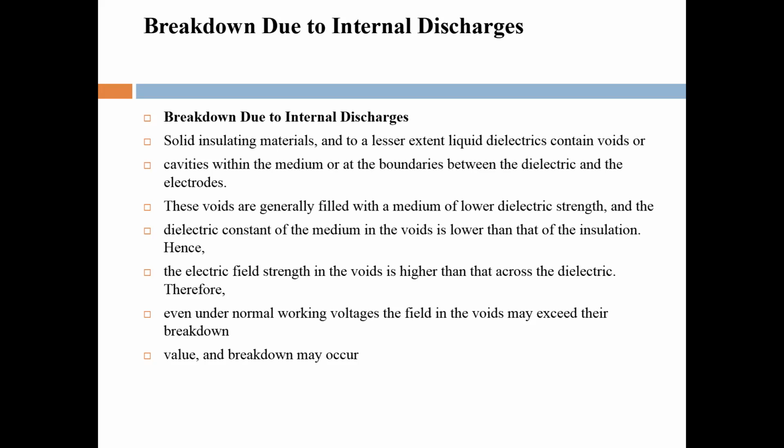Voids and cavities are formed. Due to these cavities and voids, even under normal conditions, the field in the voids or cavities may exceed their breakdown value. You know that every medium has a breakdown value. If this value is exceeded, then you can say that breakdown has occurred in the solid dielectric.